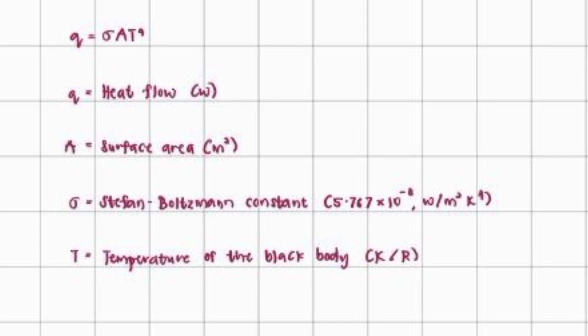This equation is used to calculate radiation heat transfer between a surface and its surroundings. It takes into account the energy radiated by the surface and the energy absorbed from its surroundings. Q represents the net heat energy radiated per second by the surface. This value can be positive or negative. Next, the Stefan-Boltzmann constant, a universal constant, equals 5.67 × 10^-8. It relates the thermal radiation of a black body to its temperature. It also ensures the units in the equation are consistent.